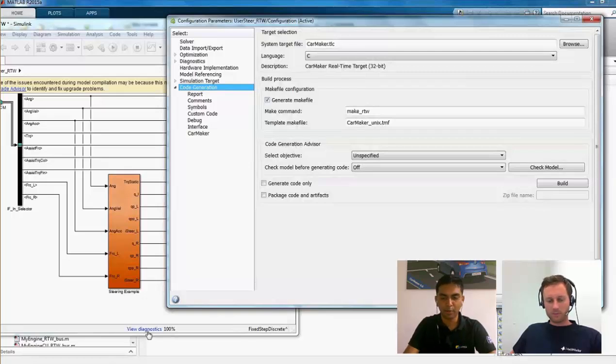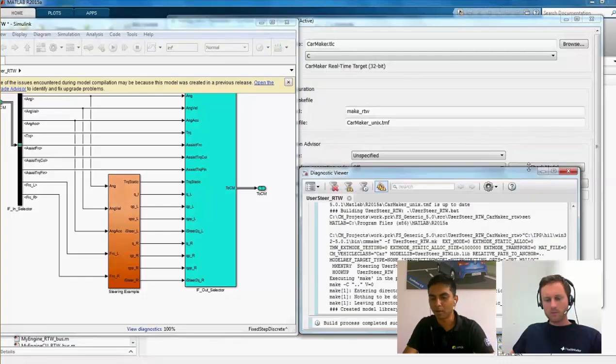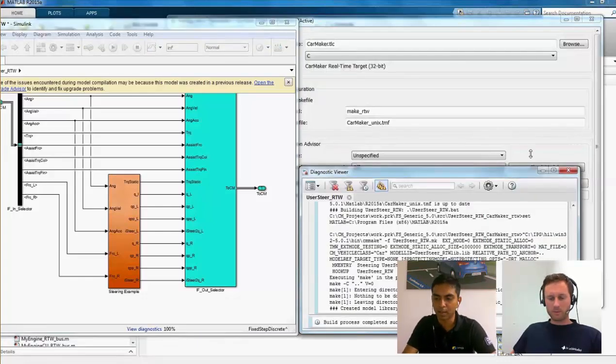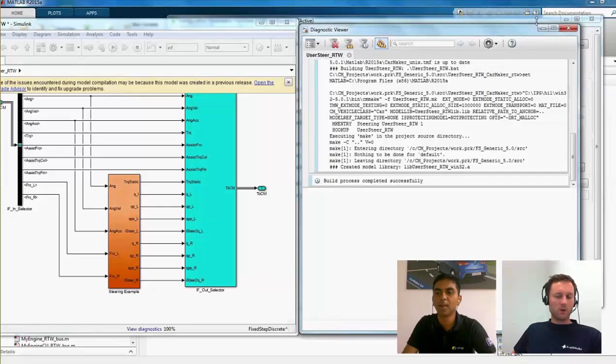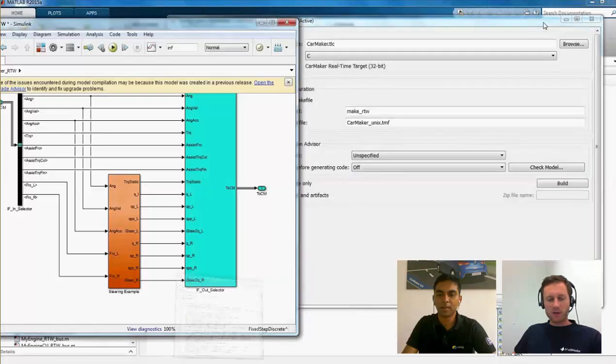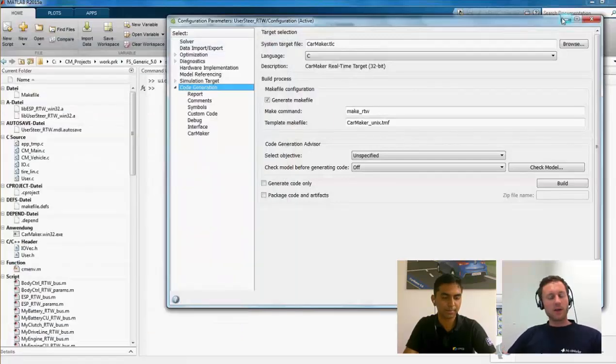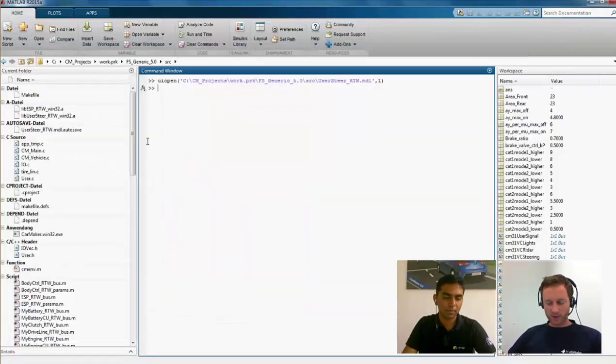See here in the view diagnostic, there's a detailed description showing how the model was compiled, what is the library which was generated, what kind of files have been created, and where the C code is living. Okay, just an amendment here, a short remark, in case you are interested in that. So the TLC means Target Language Compiler. As said, you can customize the code generation process.